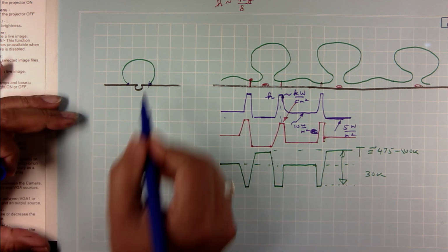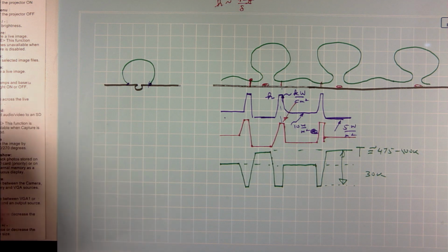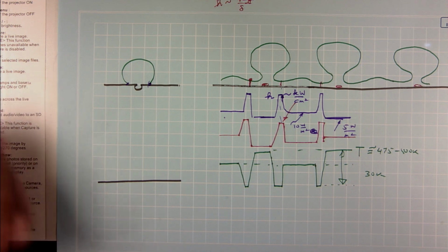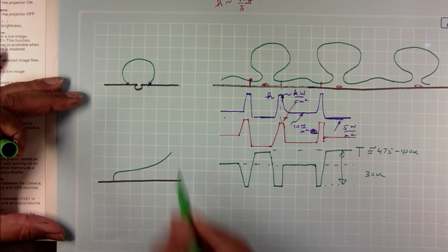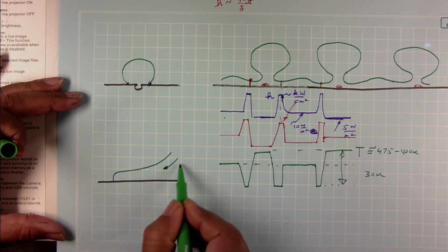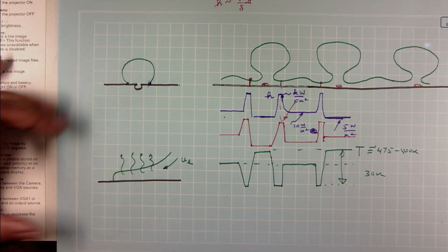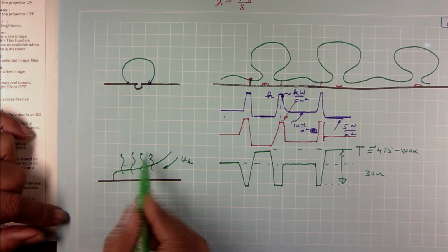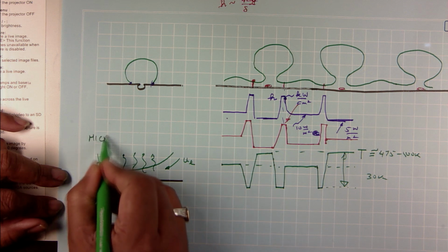Okay. So, if I magnify this area, if I look at the heater surface, this region where the liquid vapor triple point happens, it looks like this, where constantly your liquid is coming in and it's vaporizing in a thin film. The thin film evaporation we talked about, you get a sort of a thin film evaporation in this zone, which is known as the micro layer.